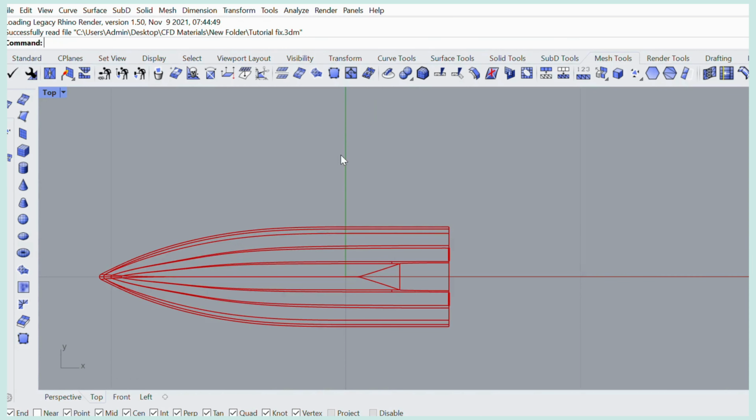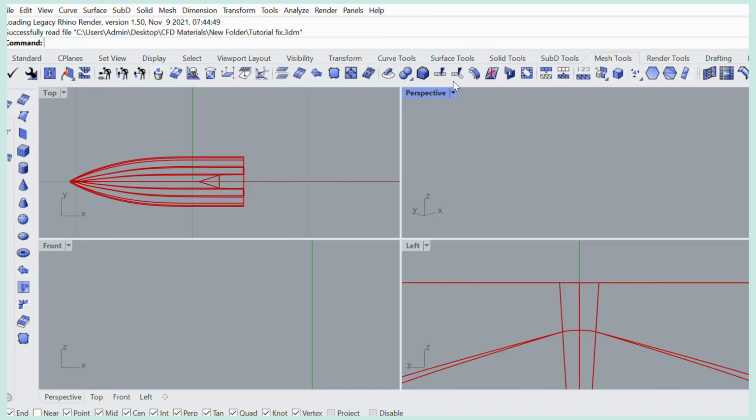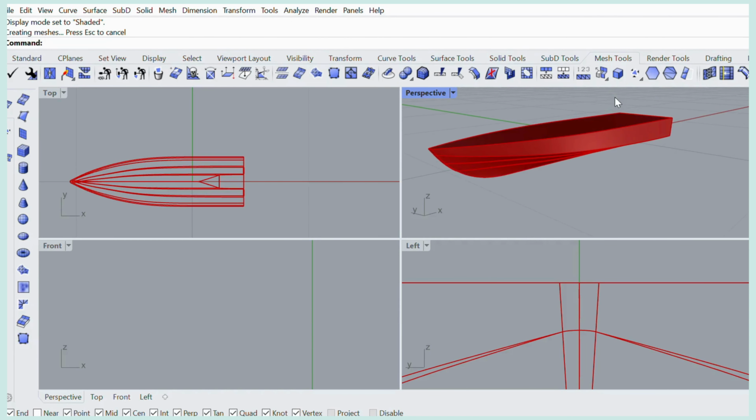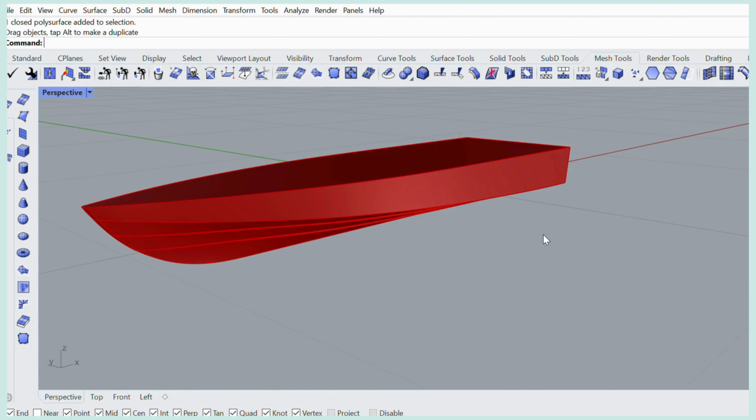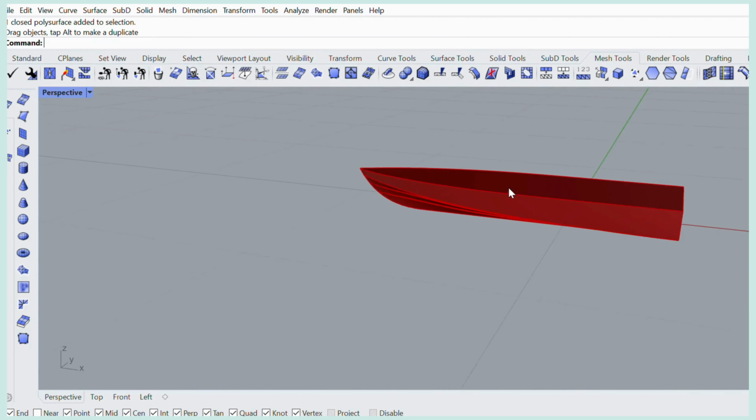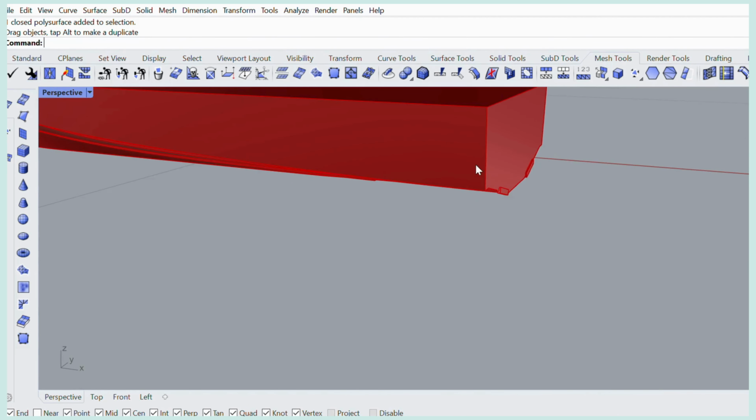I'll analyze the drag and two degrees of freedom of the ship, such as trim and heave. So, adjust the XYZ coordinate position to the center of gravity of the ship. The placement of the ship's position will greatly influence the accuracy of the calculations. Before importing to STAR-CCM+, try to find the value of the center of gravity from the baseline and also the transom.